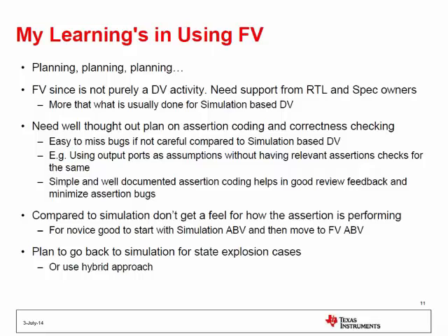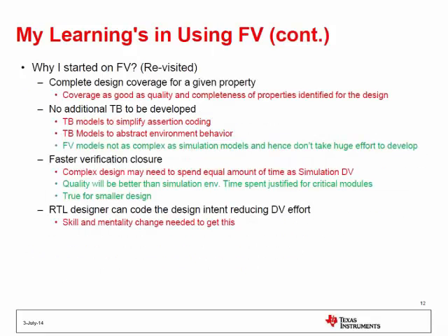No additional TB need to be developed. This again is not completely true, because you need to develop at least some simpler TB models to get your assertions simplified, and sometimes you need to develop models to abstract your environment, like the protocol example I was giving. But the models that you develop are not as complex as you do for normal simulations.